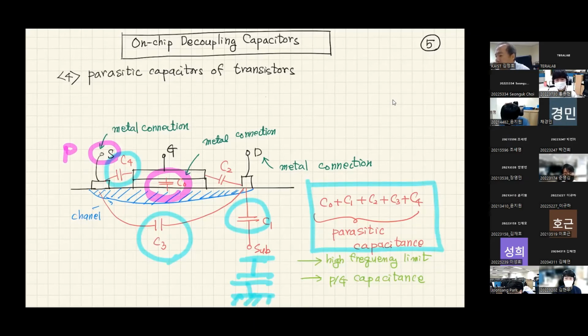So when you are designing on-chip PDNs and you want to estimate how much impedance you may have inside the on-chip PDN, you have to include all these parasitics. And you have to fight against ESL and ESR.